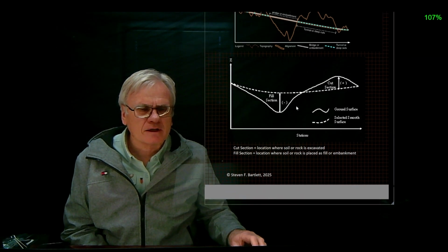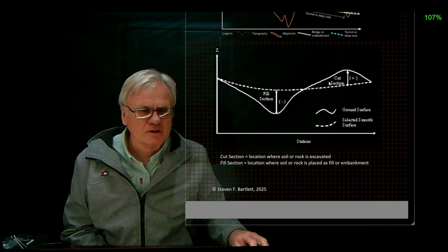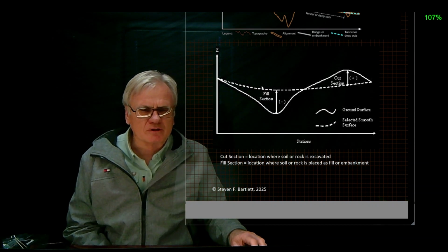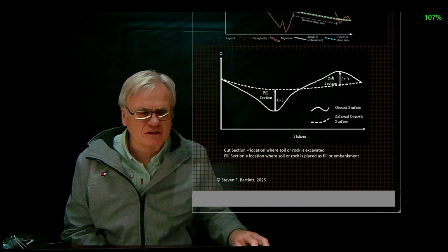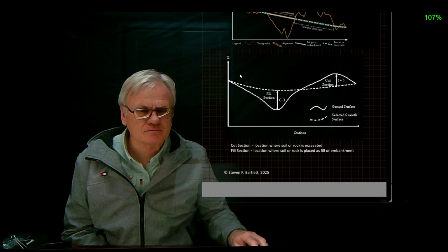So that's just to give you kind of the importance of not only getting these grade lines so that they're safe to travel for vehicles, but also there's some consideration about the terrain itself and how much cut and fill that we have to do. Obviously, trying to minimize the cut and fill would maybe give us a suboptimal section, so we do have to do some type of grading here and do some cut and fill.